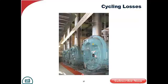This is where turn down becomes so important too. So maybe you've got an older boiler that's still in very, very good shape. You could retrofit it with a high turn down burner, or keep the same burner but do something with the overall linkage and the way it is controlled as far as the damper is controlled and how it's all configured, and add 10-to-1 to it if need be, if it's a 4-to-1 turn down. That can be done. Keep this boiler online. It seems like an oxymoron, but actually that boiler staying online is a lot more efficient than having it cycle on and off 15, 20 times an hour.